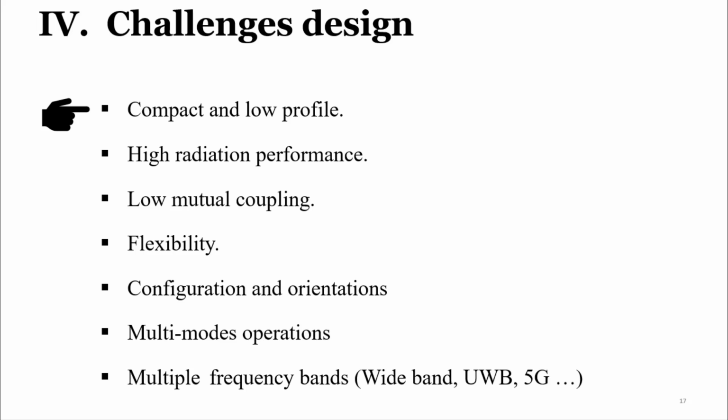So we have a method used for patch antennas that function with wideband or ultra wideband characteristics. So here, for example, if I work in the C-band, I take just an example, between 4 gigahertz and 8 gigahertz. So here, to conceive my array antenna, I want to fix a frequency because the parameters, width and length, of our array antenna have a relation with the frequency.